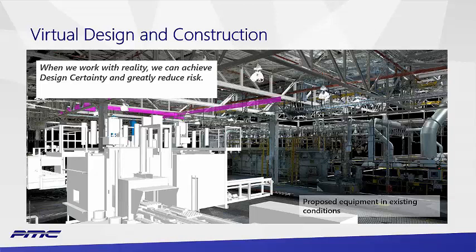Now, if we look at this, and this is a furnace, if we know that this furnace is going to fit, we can be absolutely sure that it is going to fit. There is nothing in this point cloud that is not correct, that is missing, that got overlooked. As long as we do our work correctly, this is going to work. It is going to fit in here. In this case, this project involved raising the truss to make sure that we could lift out some soot tubes out of the furnace and make clearance. And we could make sure that absolutely that was going to work.